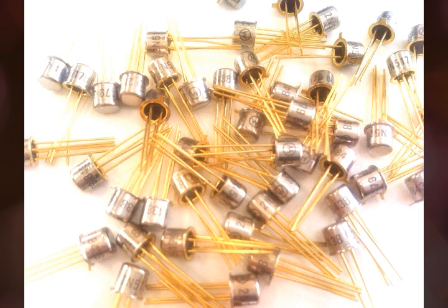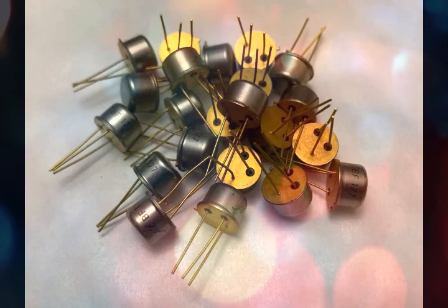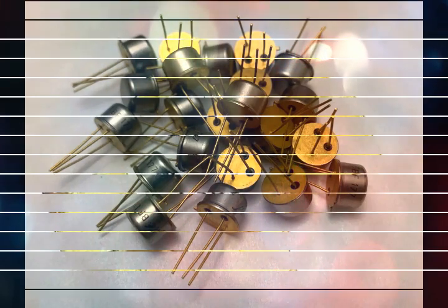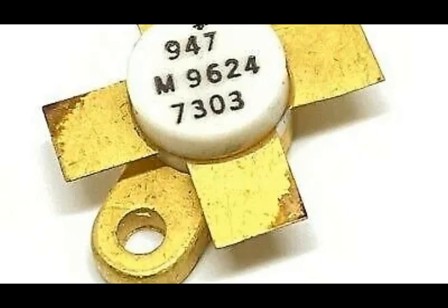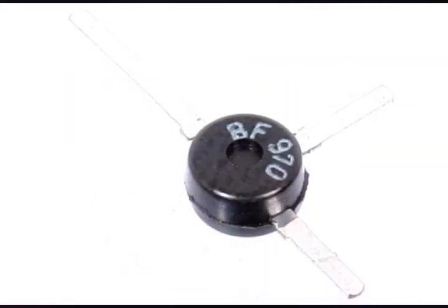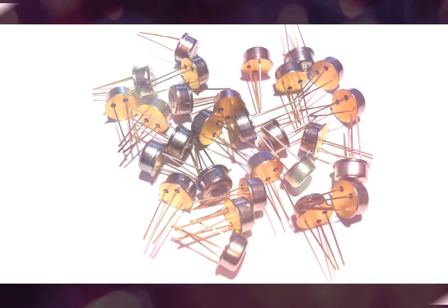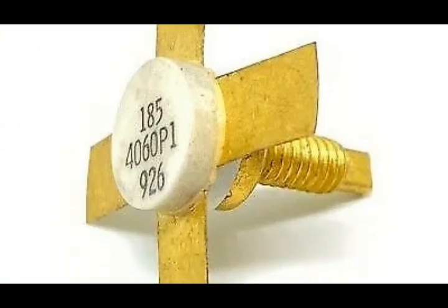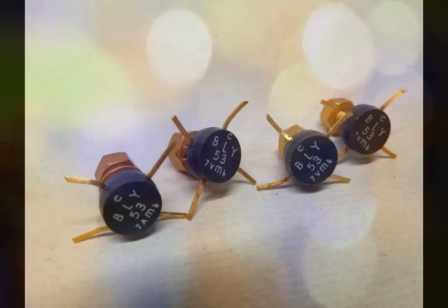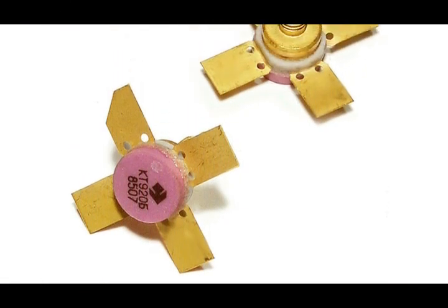RF transistors are used in high-speed switching applications, as well as for small signals operating at high frequency. RF transistors must be turned on and off at high speed. NPN and PNP types of high-frequency transistors are available in the market. These transistors have a current between 10 and 600 milliamps. High-frequency transistors are used in oscillator and amplifier circuits, such as CATV, UHF, VHF, MATV, and HF.